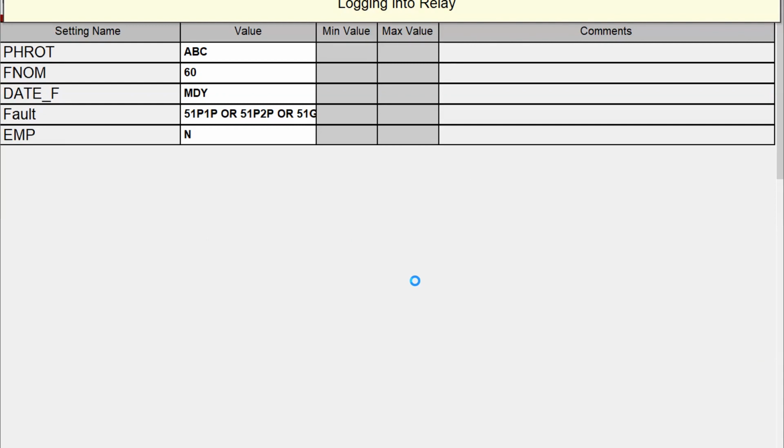The important part is that when we are connecting and trying to read the settings from the RTMS, we have to make sure that the COM port is freed up and is only utilized by the software and not locked up by the relay software. Okay. And after the relay settings are read, the settings are mapped in my test plan such that the tests are already ready to go with the test values.